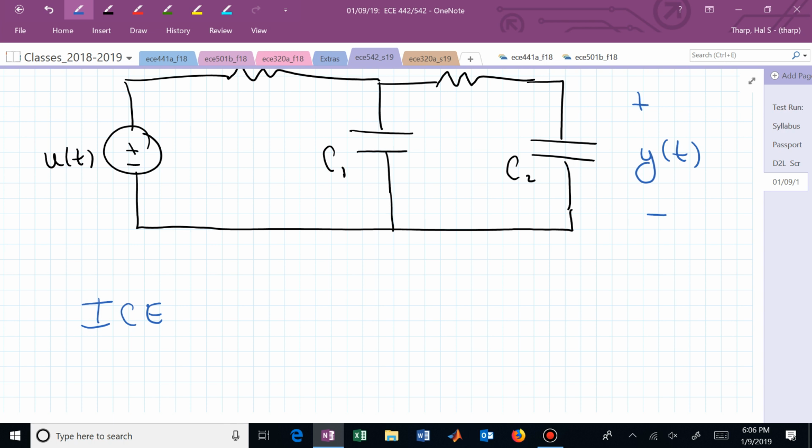But how do you connect ice with a circuit that contains capacitors? What does that acronym allow you to do? Until you retire, if somebody says Eli the Iceman, what does ice give you? It tells you the differential relationship in the time domain connecting the current and the voltage of a capacitor.